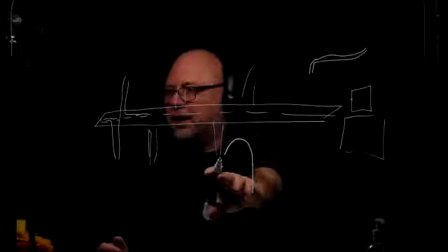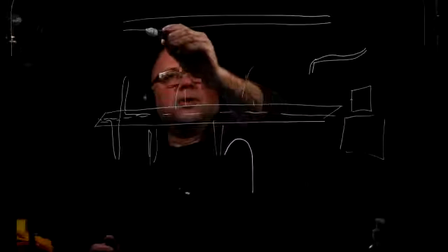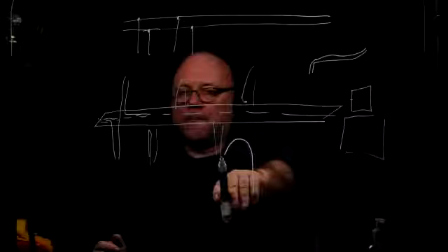So we are cutting it so we could tap in with another wire into it, and we're joining it right back together. So we are still having something like the main cable going on, and we're going to have this kind of a situation here. But we're just going to pull the wires, so we're cutting it just to join it back together and add one more cable, which means we're taking out the signal into the volume control.